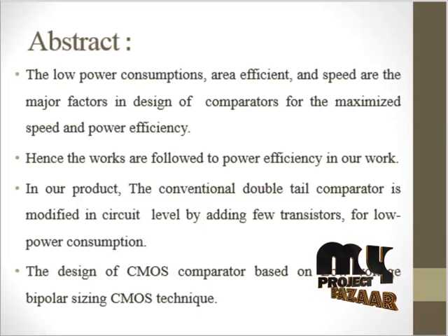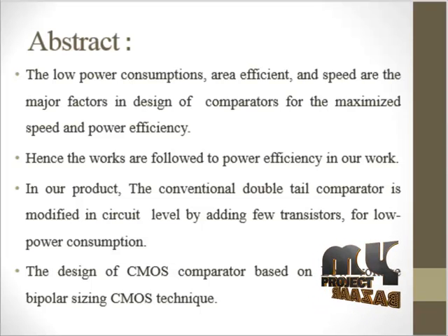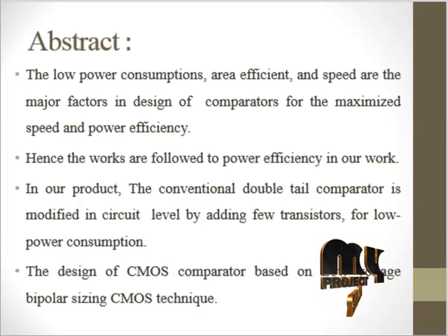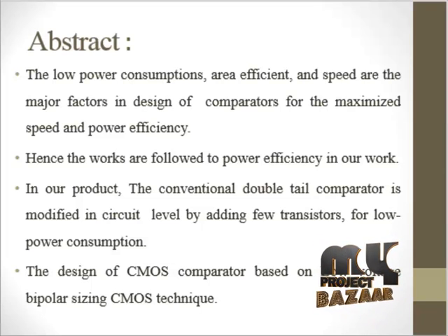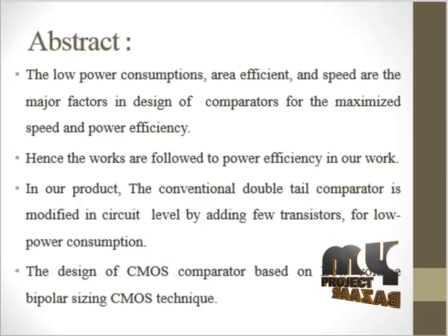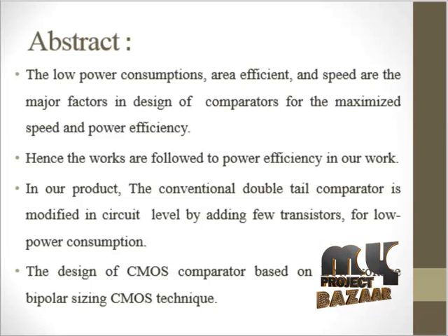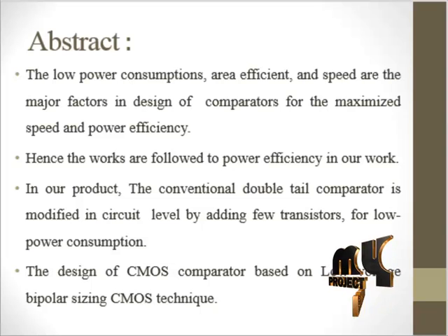The comparator is a key building block of analog to digital converters. The speed and power consumption of the comparators play an important role in the characteristics of the ADC. The successive approximation register (SAR) and flash ADC static comparators have been used, at the cost of high power consumption and low speed. Dynamic comparators were proposed to reduce the power consumption and increase the comparison speed, with a pre-amplifier stage amplifying the input differential signals.